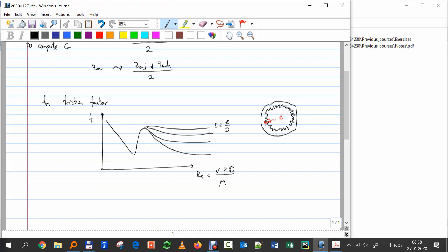So why does the friction factor remain constant in that case? Because really it's a function of Reynolds, so it should be a function of the velocity, which is a function of Q. And Q depends on density. That's local, Q local. And Q local is a function of density, and density is a function of pressure for gas. So it's changing. It should be changing along the pipe.